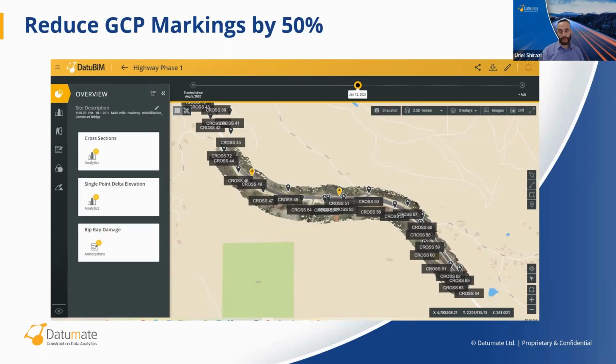Thank you, Tom. I wanted to add that we have recently, a few months ago, launched the manual monument marking for the GCPs, for the ground control points. It means that even if the GCPs were eliminated or if they're still visible in the site, we can add monuments that we detect from the previous orthophoto or from the previous model to the new images.